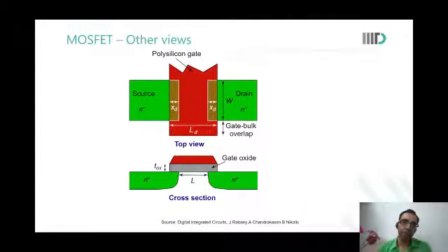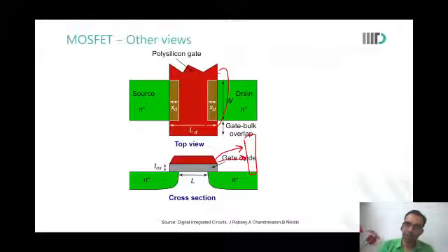So if we look at the top level view of the MOSFET, then this is how it would look. And that is the overlap region and the overlap capacitance that Gagandeep mentioned, that beneath the gate there is an overlap capacitance. But in reality, let us say there is a contact over here. There will be a gate to contact capacitance, and there will be lines of electric field which would run between the gate poly, vertical poly, and the active region, the diffusion region.